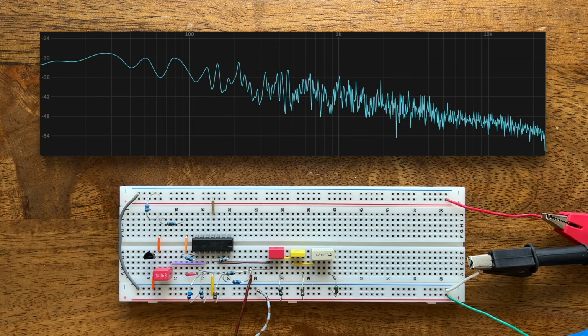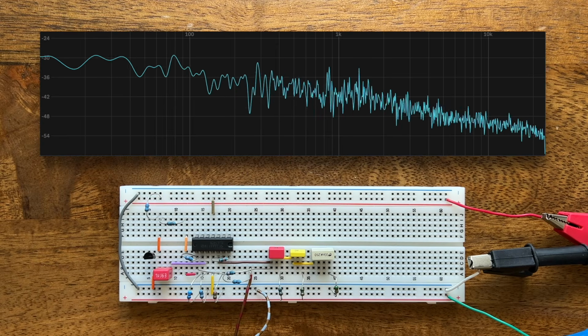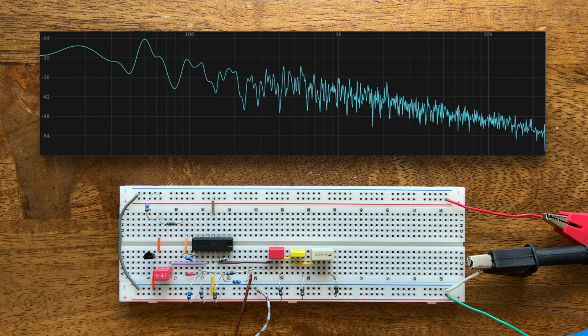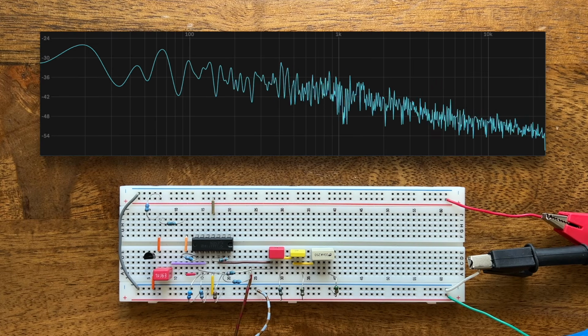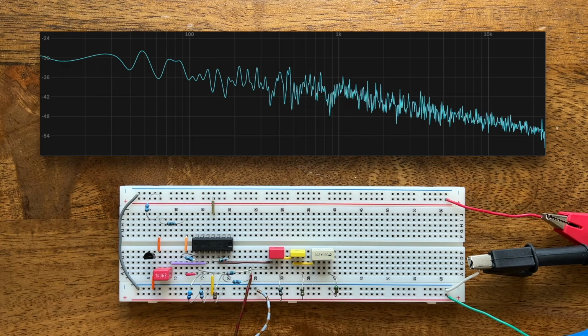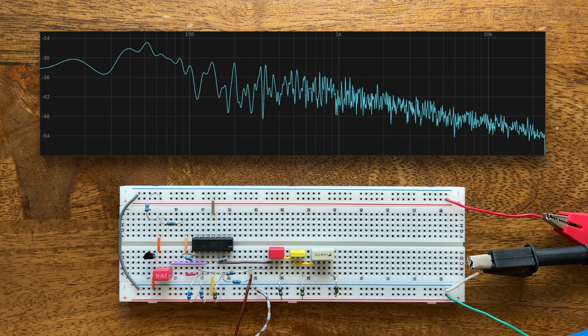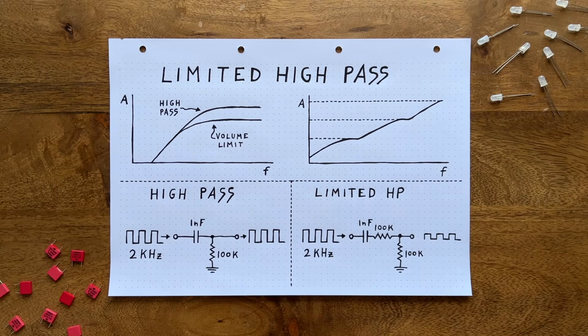And here's what the amplified output signal sounds and looks like on the spectrum analyzer. As you can see, it does indeed gradually fall off in volume towards the high end, approximately like a 3 decibels per octave slope would. And to me, it sounds pink enough. Cool, so let's move on to the white to blue conversion.